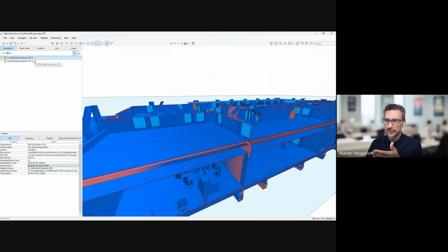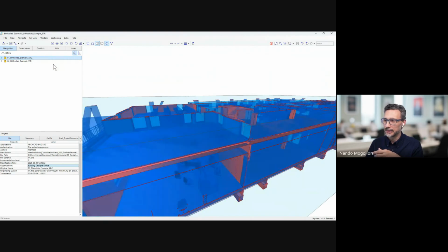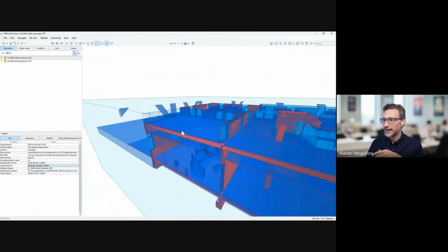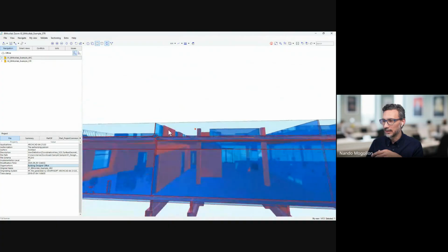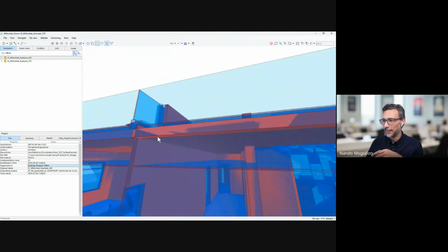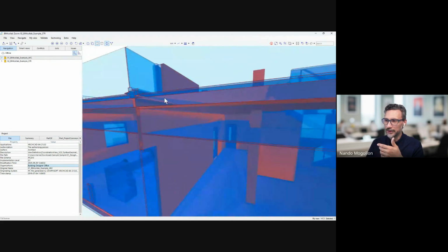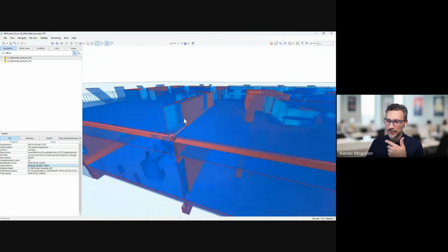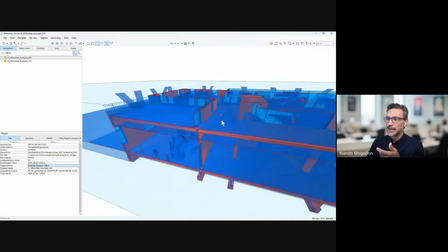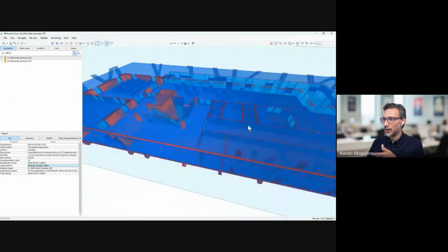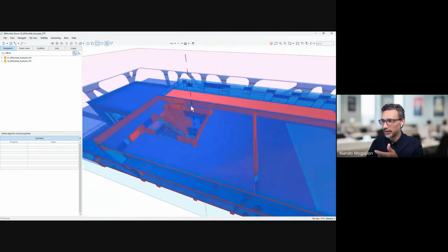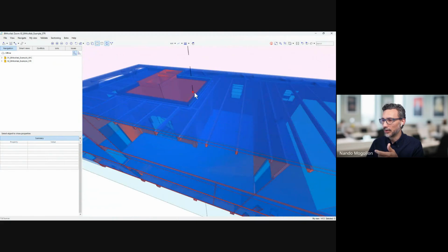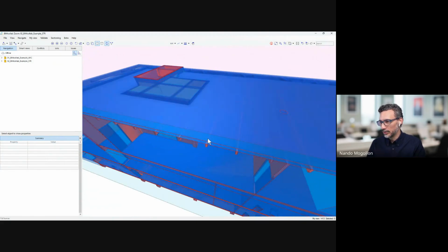So you can take the architectural model with a right click and hit Set Transparent. And if anything, what this is going to do is reveal anything that the architectural model may be covering, and you just couldn't see it because it was a solid model, right? Now, with this, you can only go so far and visually checking if the model elements are in the same place or not.